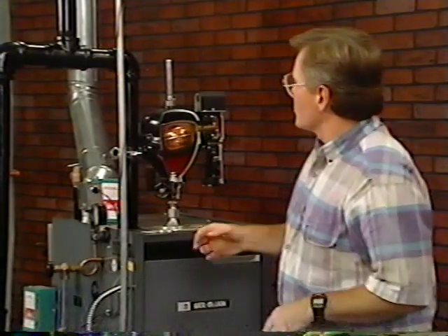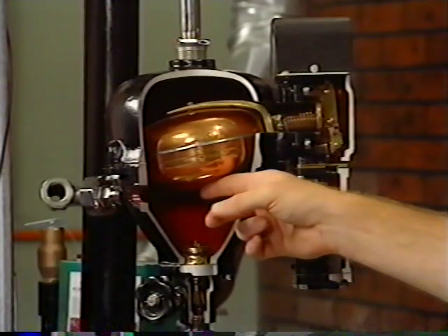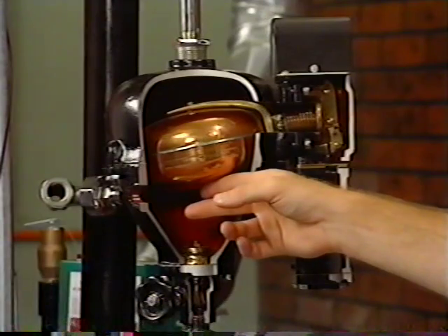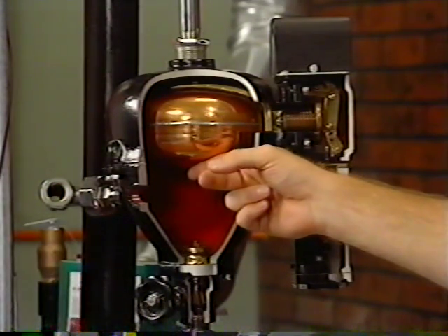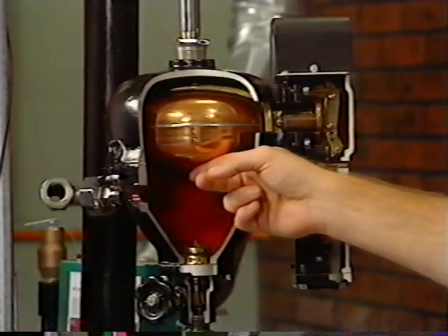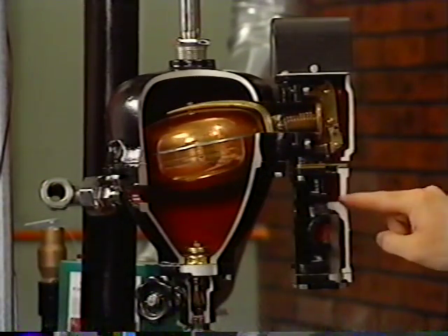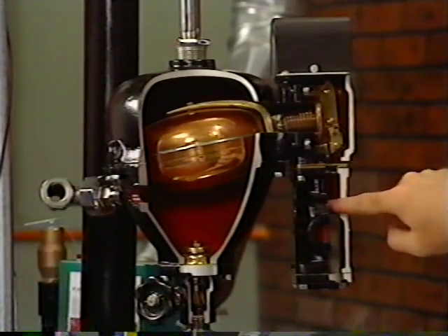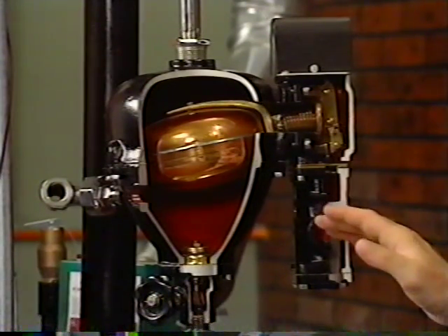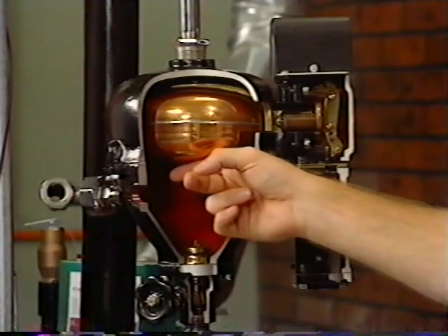On some steam boilers, you'll find a combination of low water cutoff and water feeder, or pump control. In this case, the low water cutoff operates as we've already discussed. In addition, should the boiler water level drop below the established setting, the float in the water feeder will drop and open a valve, allowing makeup water to enter the boiler, stopping when the feeder has returned the boiler to a safe operating water level.